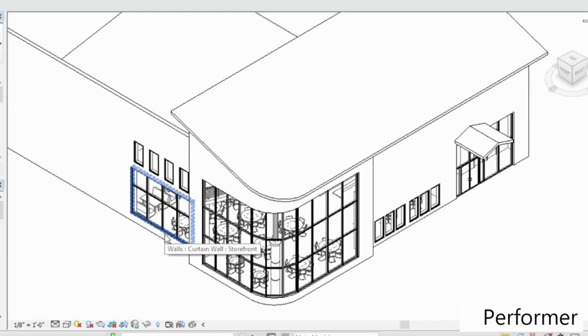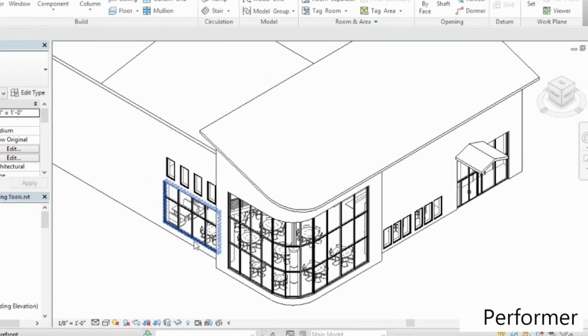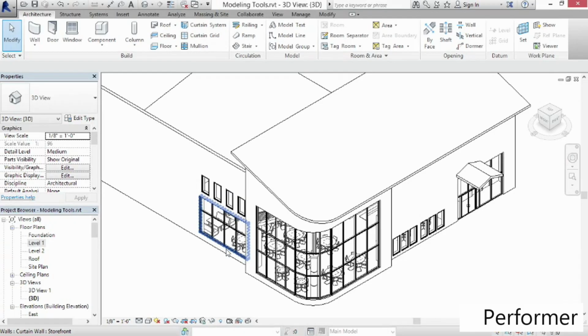Now, if you're having trouble getting it to highlight that dashed outer edge, you can press the tab key. Each time you tab, it will cycle through different options. You can see there were several there. So there's the dashed edge, but each time I tab, you can see lots of other choices. That's called a curtain wall. Now, a curtain wall is just a more complex wall that's divided into parts and pieces. It is actually a wall.